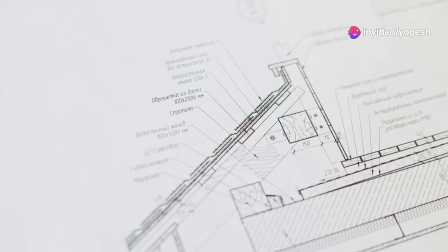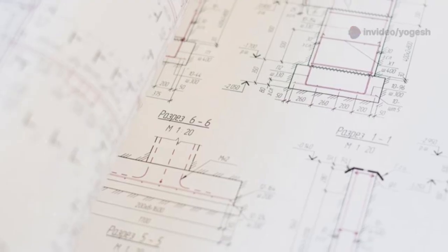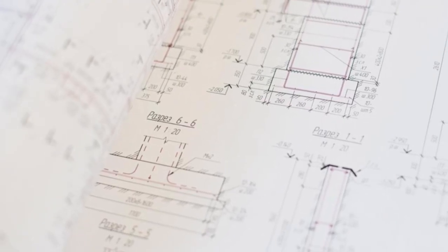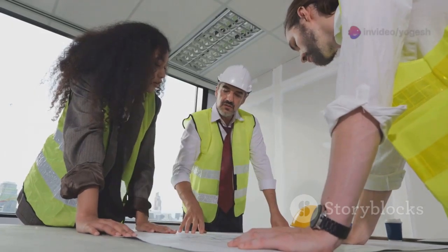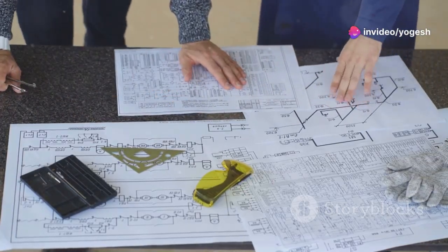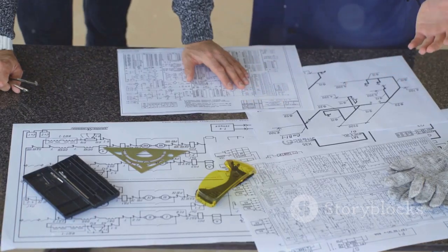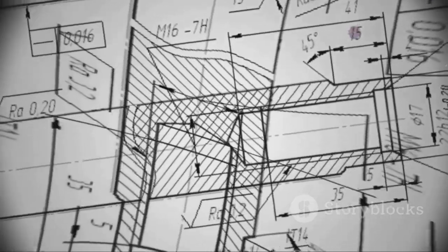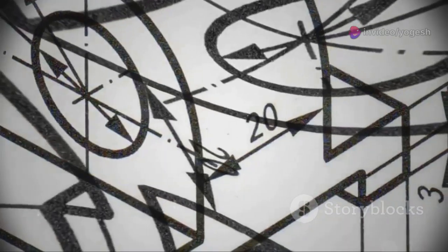Section lines, or hatching, fill in the areas where solid material has been cut. These lines make it clear which parts are solid and which are empty spaces or holes. When you put all these elements together, you get a powerful communication tool. Sectional views help teams collaborate, spot potential issues, and make informed decisions quickly. Instead of a confusing web of hidden lines, you get a clean, easy-to-read picture of the part's interior. This clarity is essential for both designers and manufacturers.